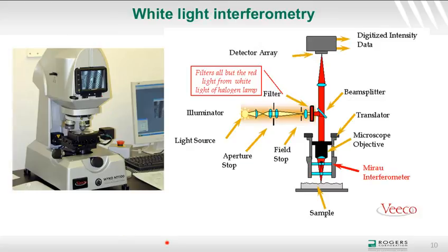The white light interferometer seems to defy physics, but not really. It is able to look at dimensions that are considerably smaller than the wavelength of light by using interferometric patterns and a very closely calibrated stage that moves. By measuring the change in the interferometry patterns, it is able to generate the surface topography in about a millimeter squared area down to about 1 nanometer resolution.